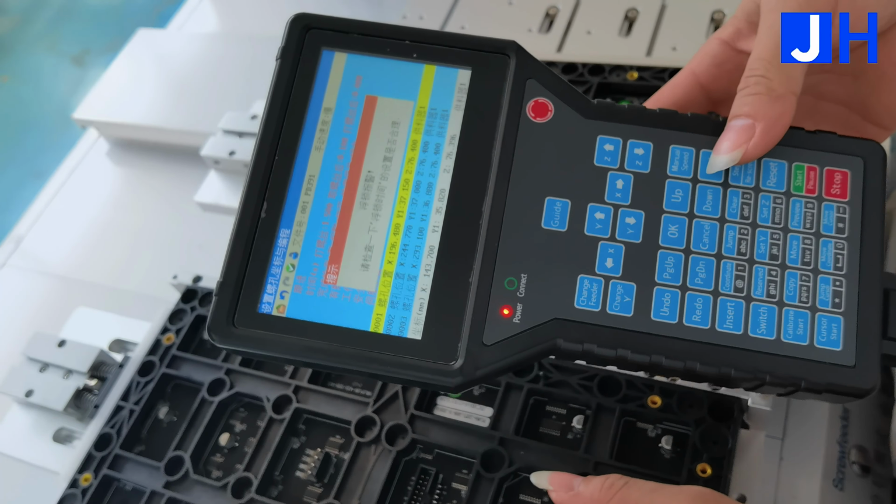Select servo configuration 1 to modify the screw tightening torque, set it to 35, and then click OK. Select the coordinates of the screw hole and click single step. The machine sounds again. This is an error in the timing of the assembly screws. You see, the screws have been assembled, but the alarm still occurs. Because it completes the screw assembly in 0.3 seconds.